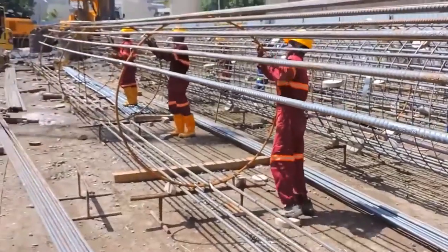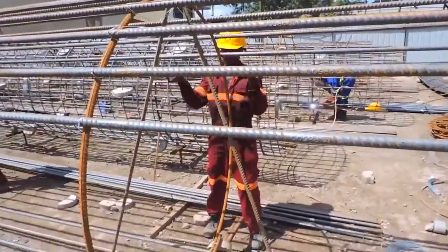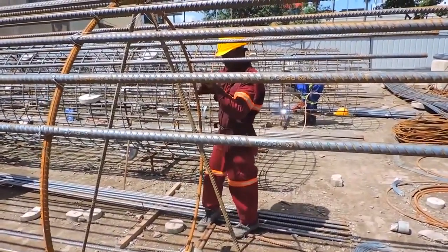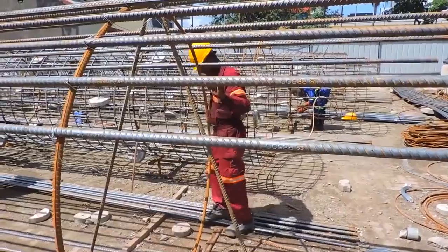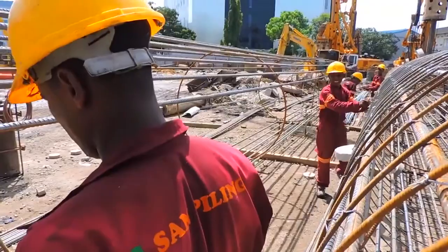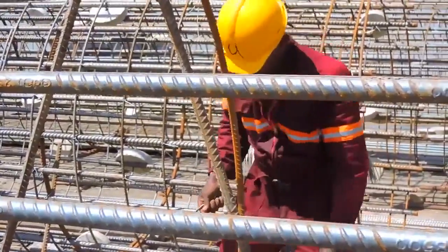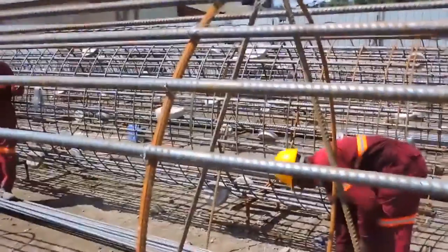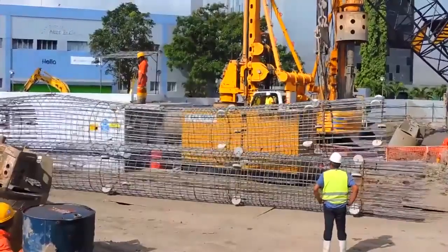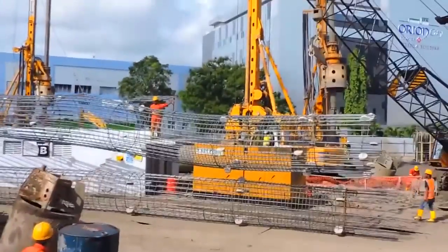The next big mission is concreting. Prior to concreting, a few tasks should be done. First, the reinforcement cage should be fabricated. It should be done while the drilling operation is going on. Before inserting the reinforcement cage, the pile should be washed by circulating bentonite. Then reinforcement cage installation should be carried out by using the crane or the BG machine.